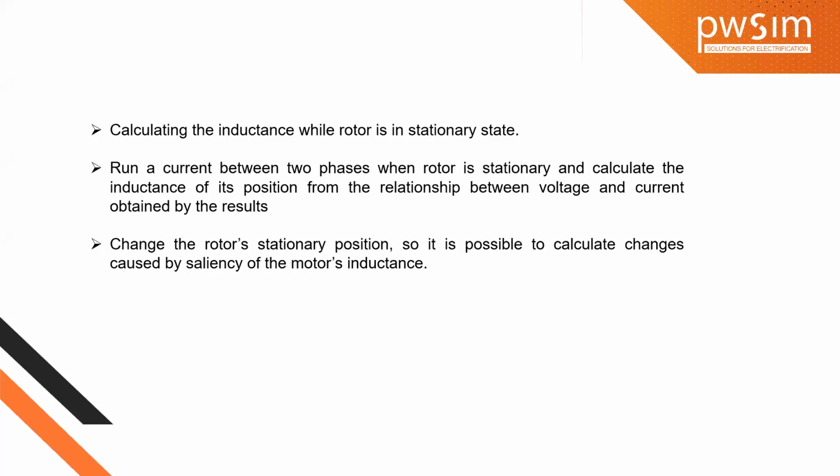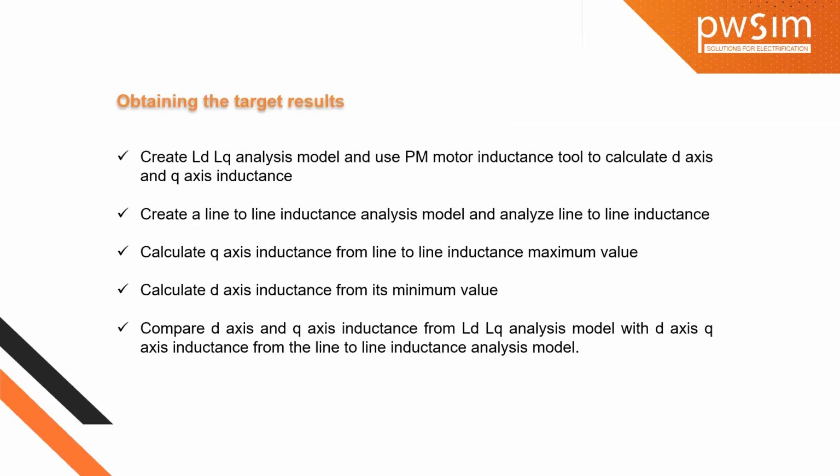Here there is no interlinkage between the rotor magnet pole and the rotor magnetic field. In this case, the torque is created by the magnetic resistance saliency, which is what I meant by reluctance torque. Reluctance torque is generated by magnetic saliency, and the magnetic flux flowing inside the rotor plays the key role. The motion is complicated because of the rotor geometry and the relative positions of the magnetic fields, so the current dependency is on the data of two axes, namely the d-axis and q-axis. By using the actual measurement of the inductance or with the help of a tool, we can easily simulate our result.